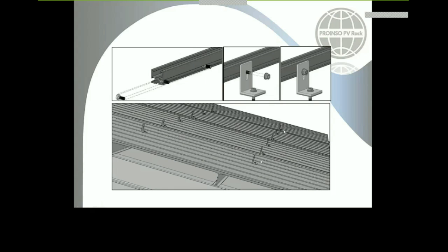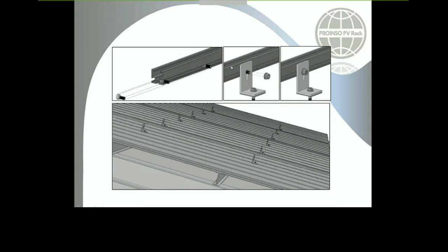Here, there's one example of how they have to be aligned, okay? And when you have everything in place, it is the moment to install the rails. As I previously said in the tile version, you slide in the bottom shape, but in this case, we are going to slide our screw in one of the sides, okay? So you slide the screw up to the connection that you are going to fix, and you tighten your fastener, okay? When you have everything in place, the next step would be the clamps connection.